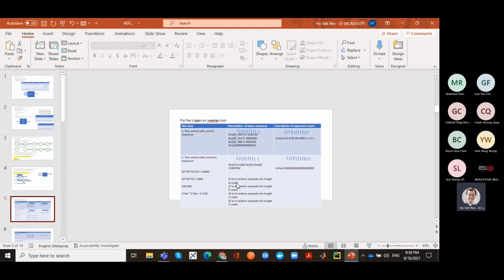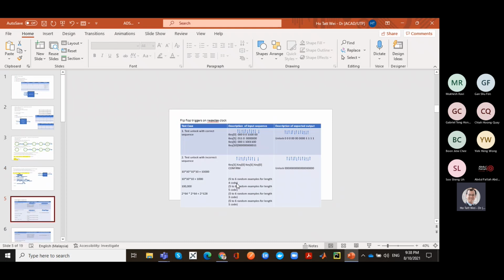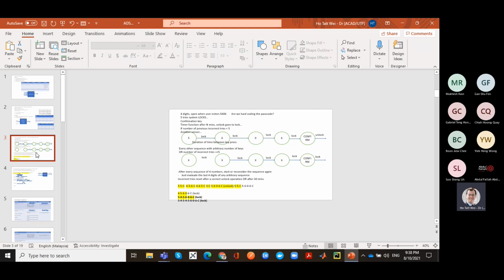So this goes back to, you have to really define the test cases. That is the specific patterns of inputs that you are going to send into your circuit. And you have to describe what is the expected pattern of outputs for every single specific pattern. And we went through an example of that with this log example, where as we started building the specification, we first did the cases that we knew were expected inputs, but then we started building all the unexpected inputs.